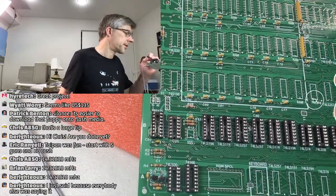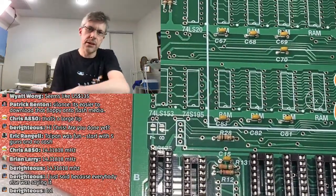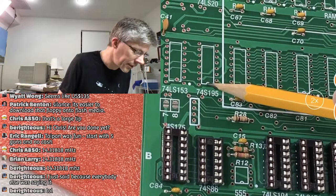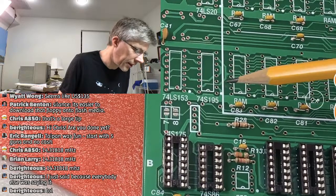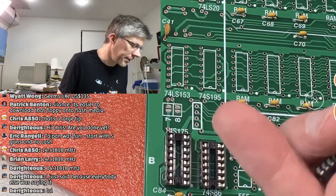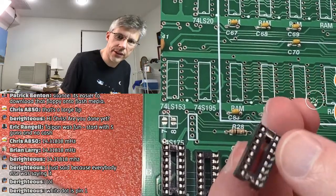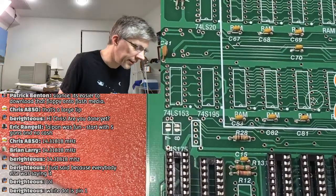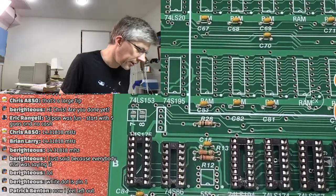So for each one of these sockets, let me zoom in here. You can see, for example, this 195 here. This has a little notch, which indicates the orientation of the chip, and then it also has a little dot here which indicates pin number 1. Obviously, you don't want to put a chip in backwards, and so the sockets will also have a little notch on them, and you just want to line up that notch with the board. You should triple check these before you do it, because you definitely don't want to screw them up.